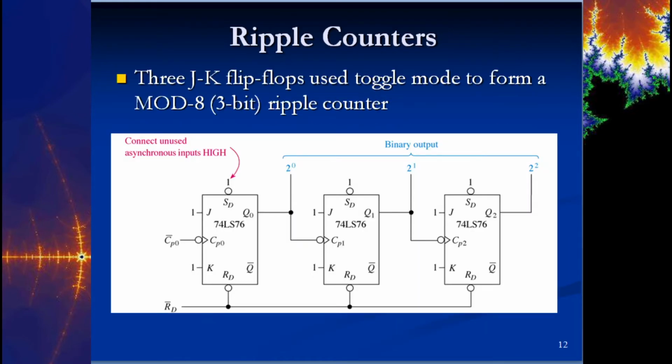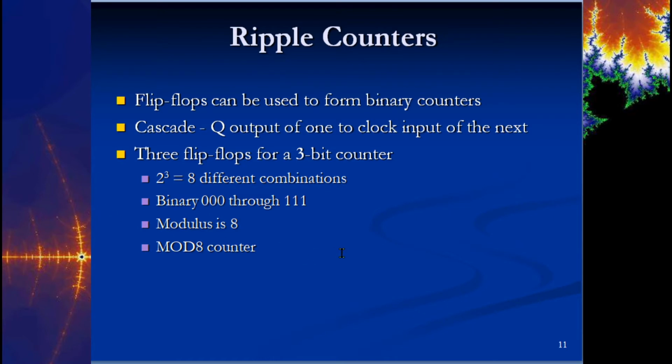So let's go ahead and talk about the ripple counter. Right, because this is what I'm going to spend the majority of my time on, because I want to get to the point where we are creating these divide by n counters, and you should feel comfortable whether I tell you to do a mod 17 or a mod 4. You just need to determine how many flip-flops you need and what your reset conditions are. So before we talk about that, we're just going to talk generically about a ripple counter.